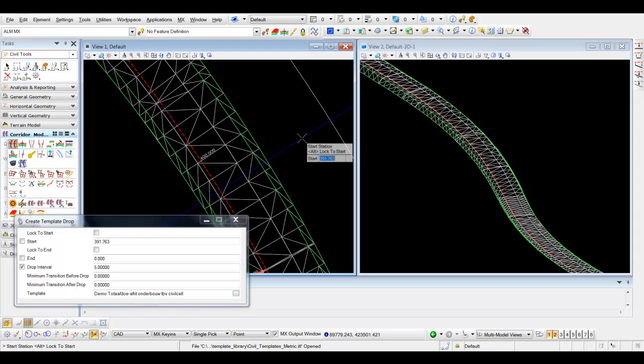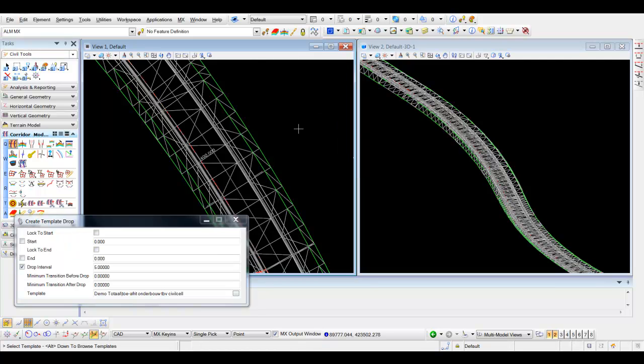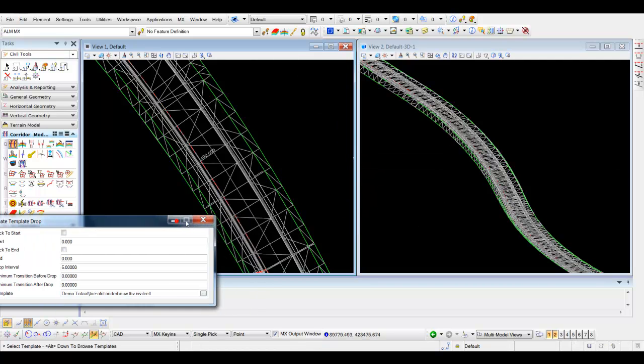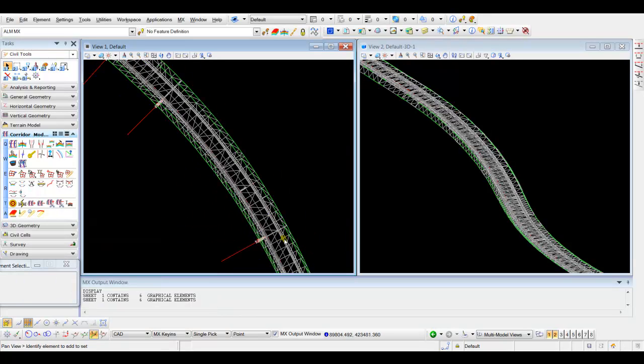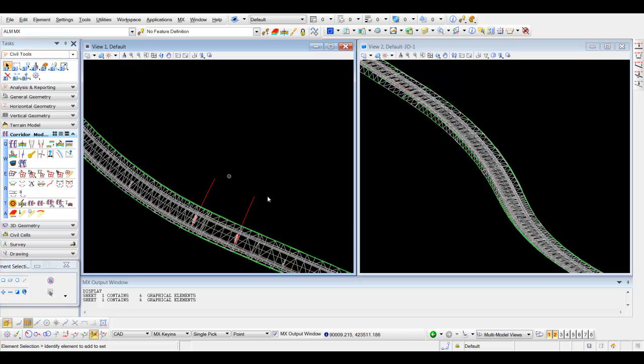And then I'll let the template drop start at chain edge 50 and then until the end. I'm putting in 50 now, so I can select my road edges more easily, and I can display the components later on a little bit better.